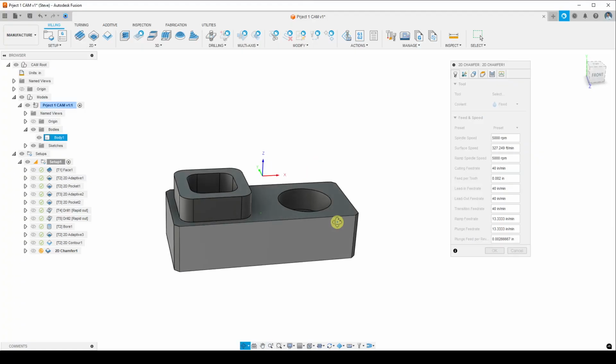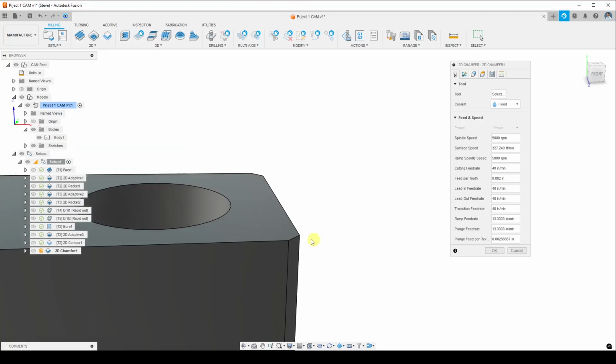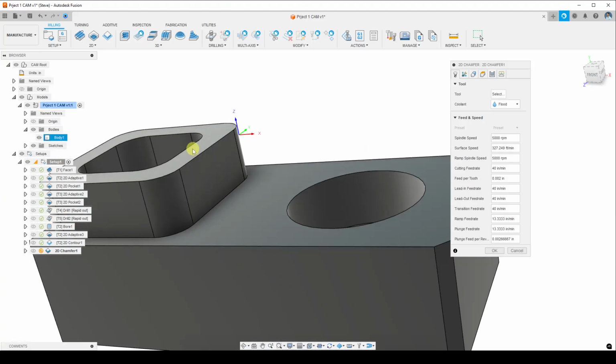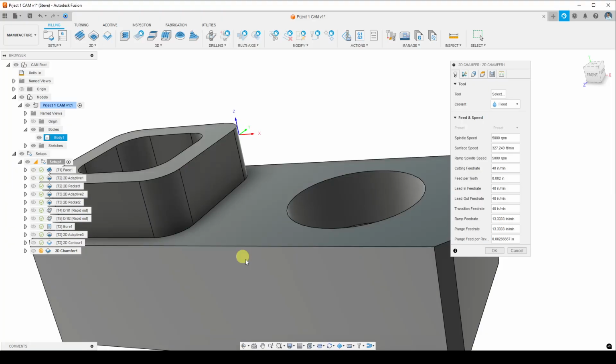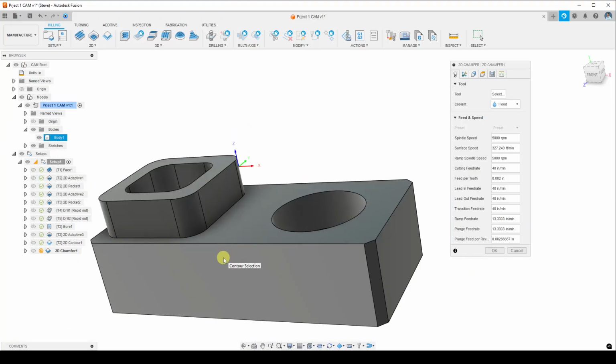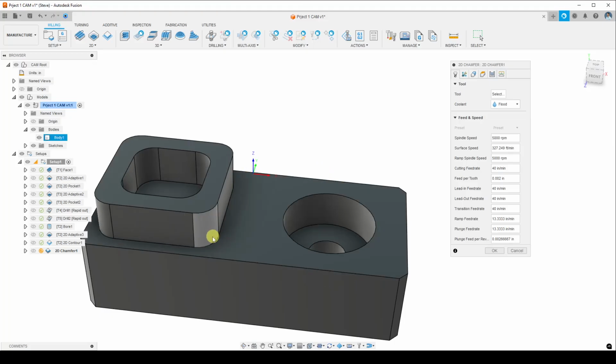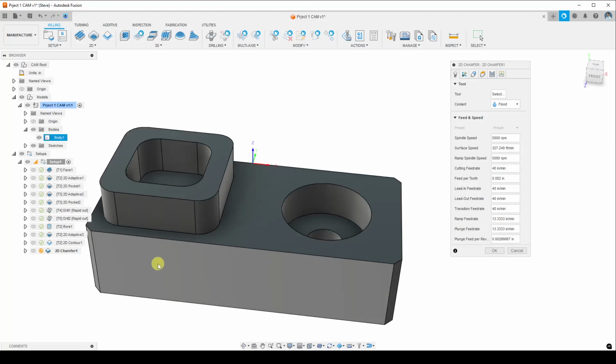When it's a machined part and you've machined the top and you've machined the side, you oftentimes have a burr of very sharp material left along that edge, and they can even cut you. So we're going to make a chamfer on all those edges, and then we'll hopefully do what's called breaking the edge.